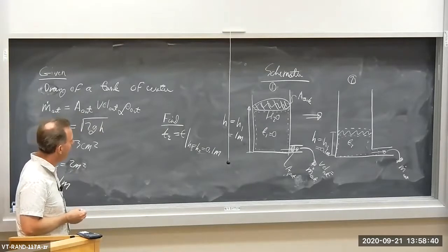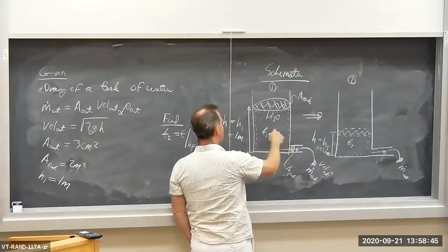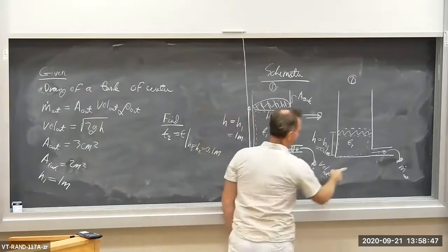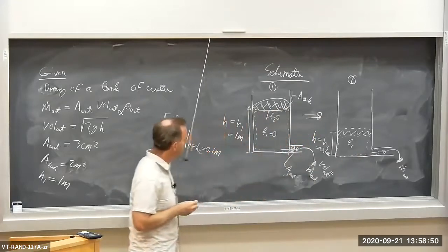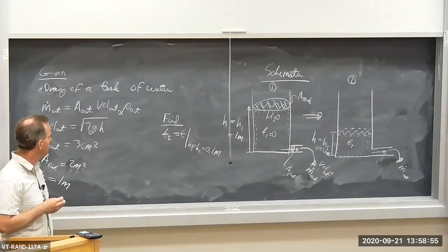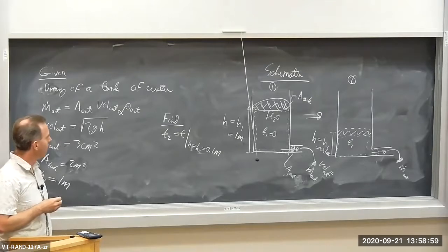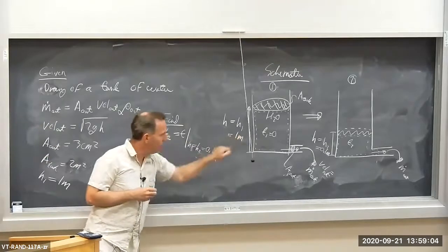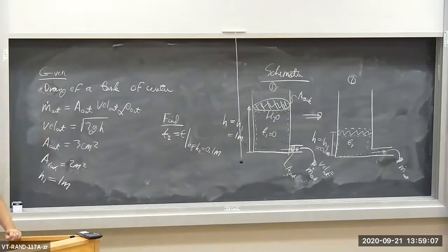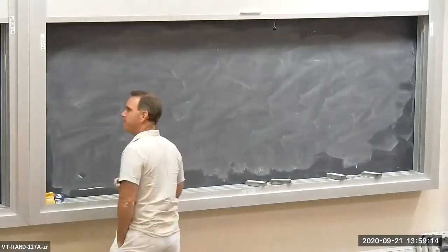All right? Okay, so we've defined the system as encapsulating the liquid H2O inside of the tank, and over time H2O leaves the system at the outlet at the bottom. We want to know how long it takes to drain 90% of the H2O liquid away, starting off with an initial height of 1 meter. Okay, let us apply the mass balance to this open system. We have one outlet, so clearly this is an open system.